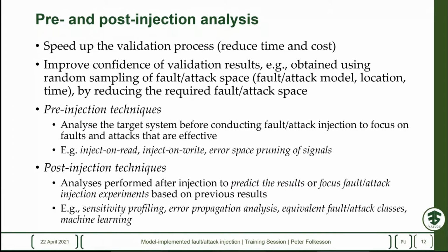We investigate two techniques for this. First, we are looking at pre-injection analysis, where we analyze the target system before injecting the faults and attacks, so that we may focus on the faults and attacks which are effective and whose results are unknown. Some techniques we are looking at here include inject-on-read, where we only inject on signals when they are read; inject-on-write, where we only inject on signals when they are produced; and pruning of signals, where we identify and eliminate equivalent signal locations in the target system model.